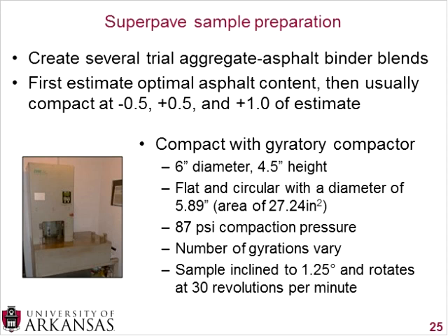And it was believed that this is more representative of a compactor in the field. So when you think about a steel wheel compactor, that generally kind of pushes the material down. It does not hammer it down like the Marshall, or tap it down like the Hveem. It's trying to be more representative of field compaction. Now, of course, as researchers, we like debating just how representative it is, and there have been arguments that this circular motion isn't representative of the compaction in the field. But at this point, it's pretty much the best that we have, so it's what we're using now.